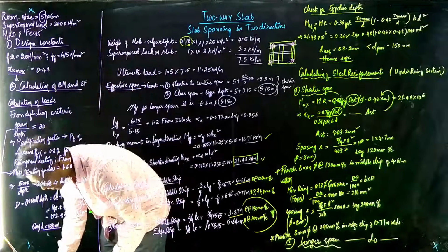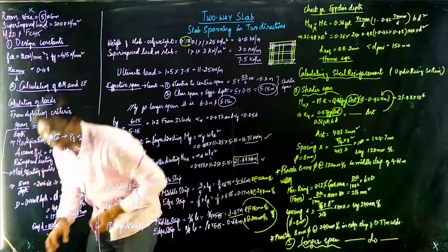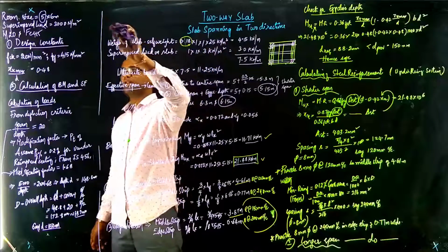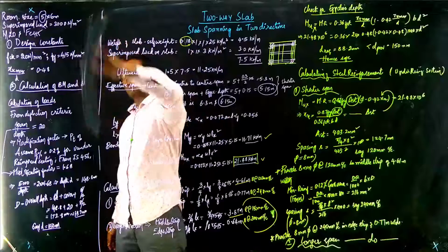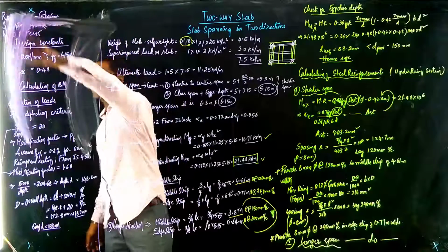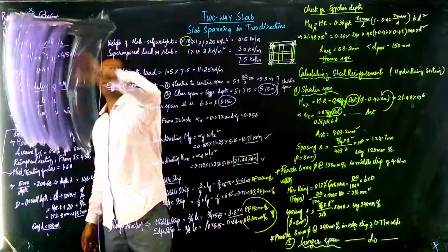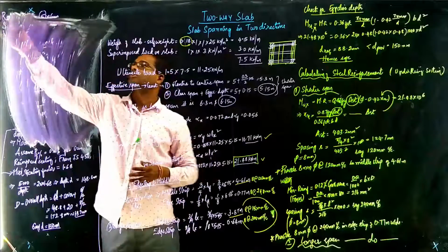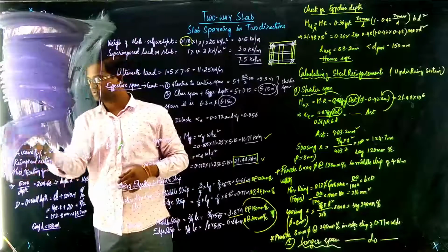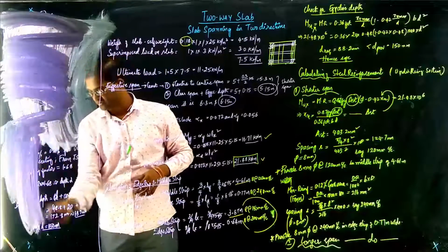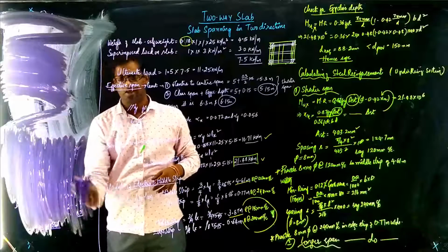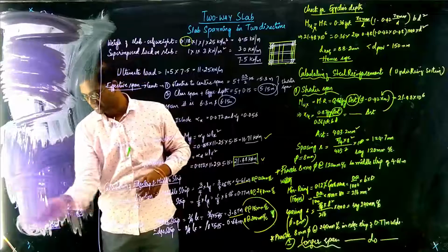If you take a closer look at the annexure, that is slab spanning in 2 directions, it is clearly said that when slab is held down or slab is not allowed to lift up, you have to provide a torsional reinforcement of certain amount, and those clauses are given.